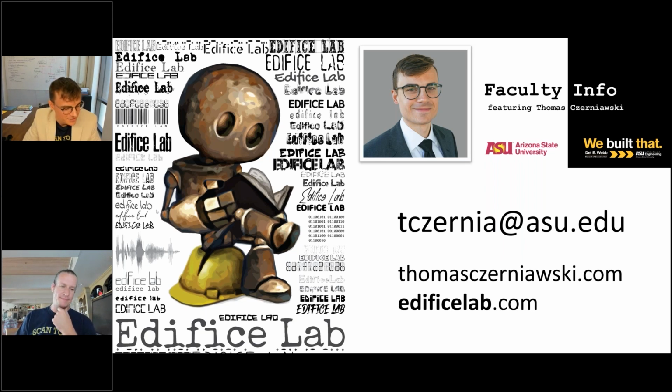And then there's a smaller company. I think their website is like scantobim.xyz or something like that, where they do a bit basic semi-automated, where you click on part of a point cloud and it fits a pipe to that section. If I'm not mistaken, Faro has some capability to do that as well. Yeah, Faro, Trimble, all of them in their software that they package their scanners with, they'll do some semi-automated stuff. So fitting of pipes, lots of user input, but certainly way more accurate than manual tracing.